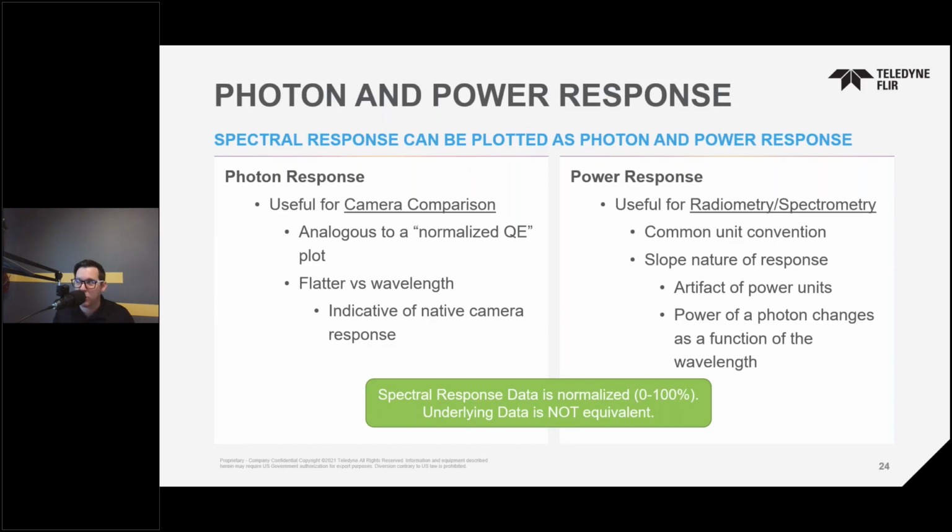If you don't know how to use a spectral response measurement, then you likely just do not need one. So don't worry about it. These are usually only important for custom cold camera work and precise radiance measurements, commonly, again, ordered with custom cold filtered cameras, and more commonly in the target signature crowd. For the purpose of just comparing products, there's not really a need to pay for a response measurement. The typical responses that we can provide for free, like I mentioned, on FLIR.custhelp.com, those are going to be sufficient.